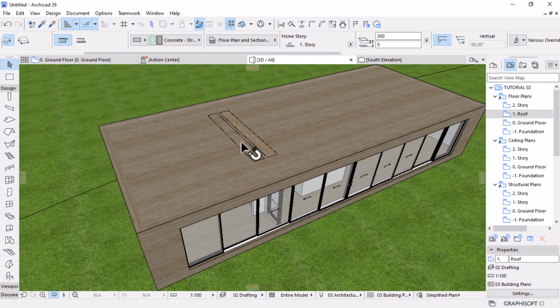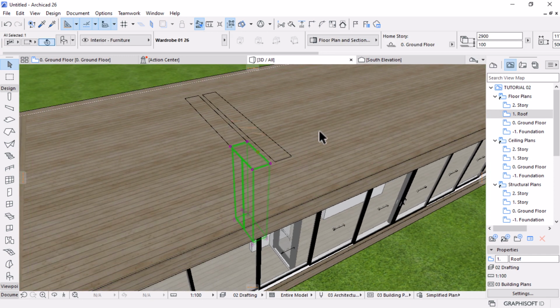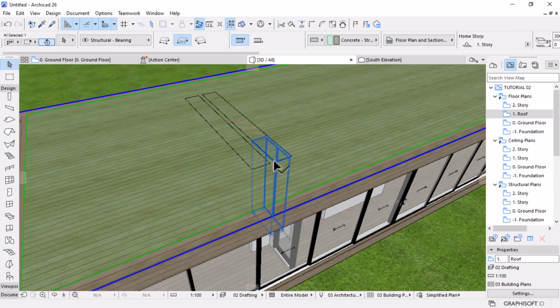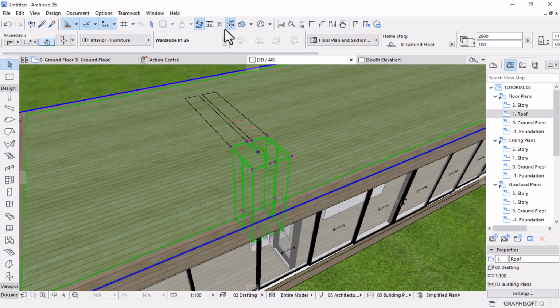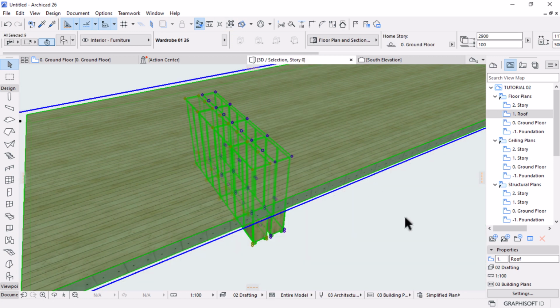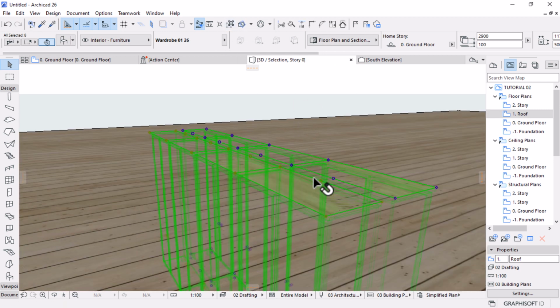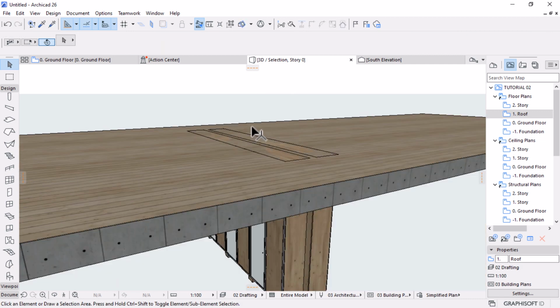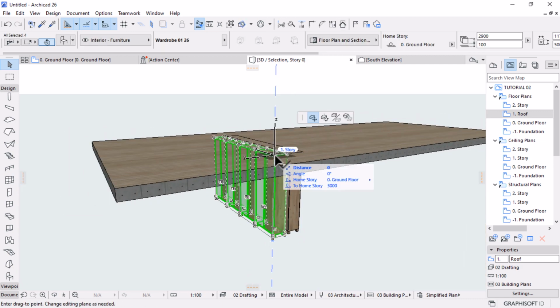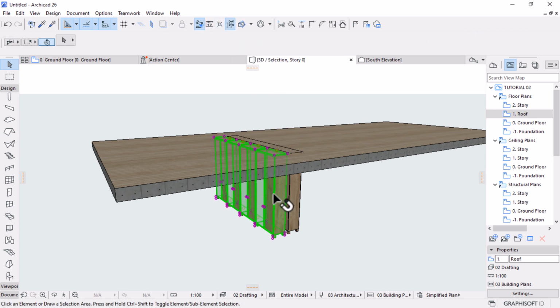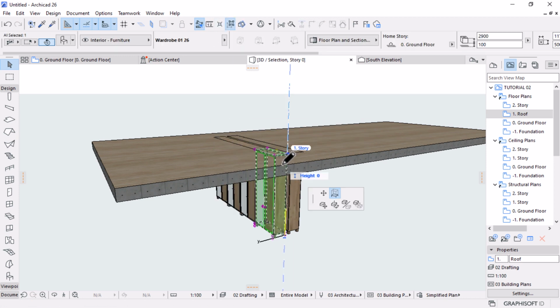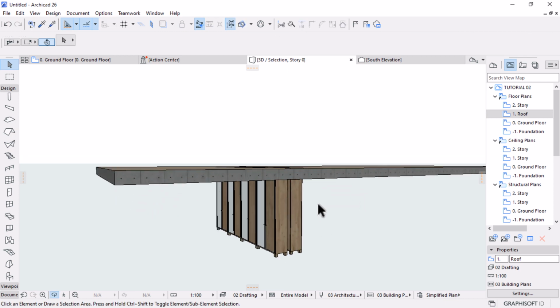Okay, so we have an encroachment of our cabinetry here. What we can do is select both the cabinets for the closets, suspend group, and then hit F5 to isolate them. What we need to do here is deselect the slab, and then pick one, and then stretch the height to the underside of the slab.